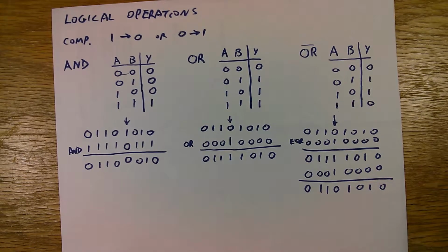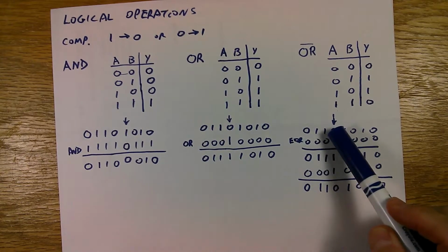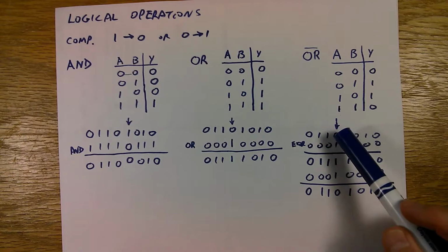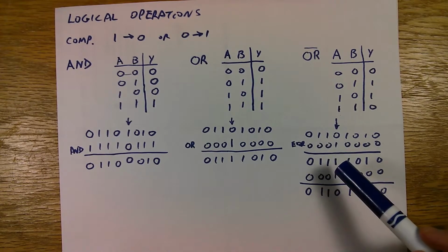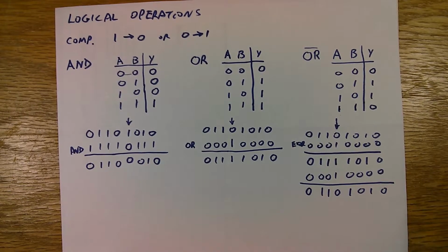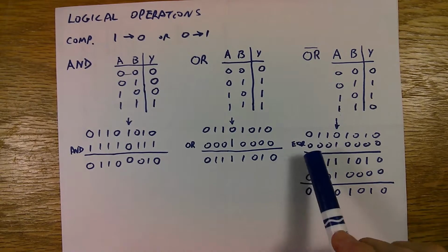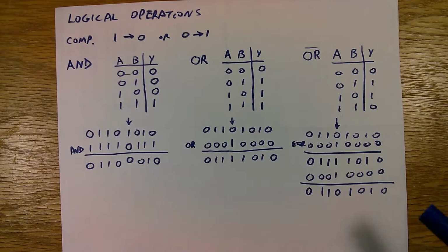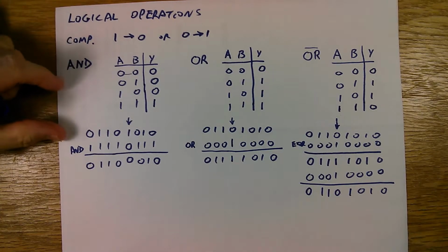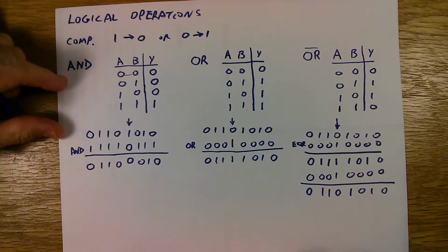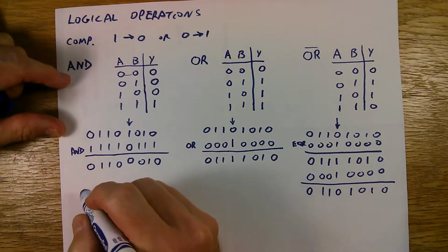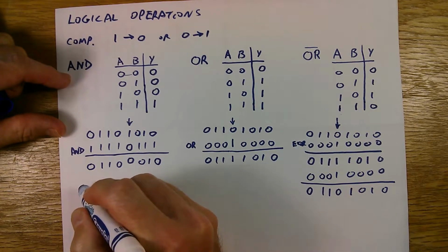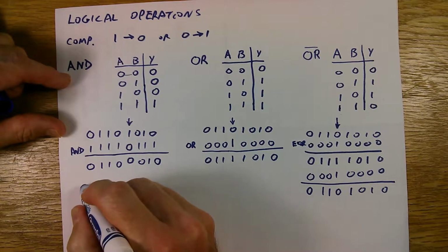Another way of doing it is more complicated. I could look at that bit, and then if it's a 0, write a 1 to it. If it's a 1, write a 0 to it. But that takes more code to do that, instead of just simply exclusive ORing it. The symbol used in code in the software for ANDing is the ampersand. I'm not very good at writing the ampersand here. How does it actually look?